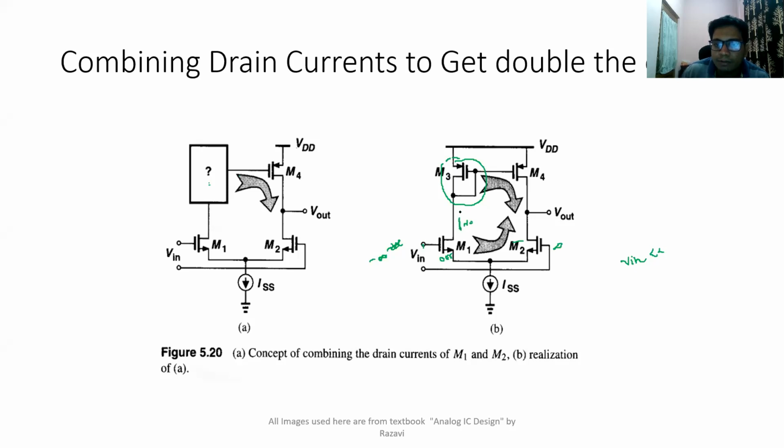Okay. Once there is no current flow here, this current mirror tries to be alive. Any circuit, whatever you connect, if they're in feedback configuration, they will try to switch on themselves. Even if this circuit tries to switch on, it will not have sufficient VDS to make it switch on. So VDS will be 0 because there is no current flowing here. There cannot be any voltage drop here, so there will be no voltage between drain to source terminal.